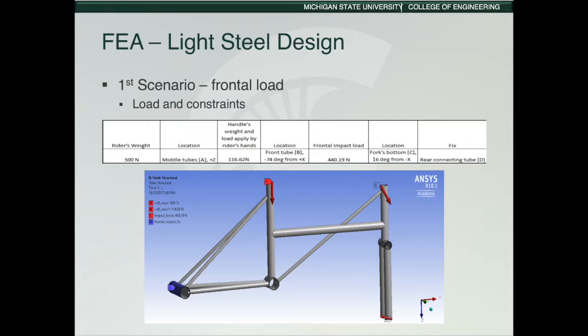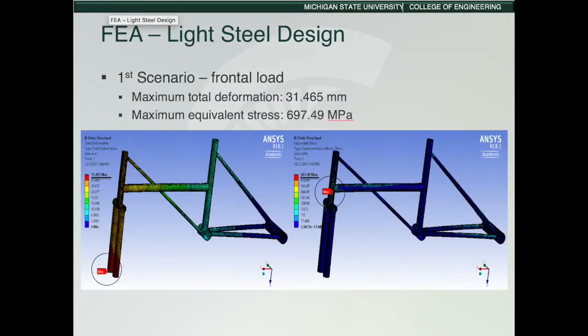We fix the connecting tube, which is D. This is the total deformation distribution after analysis. The maximum is here, which is 31 mm, and for stress, the maximum is here, which is around 700 megapascal.